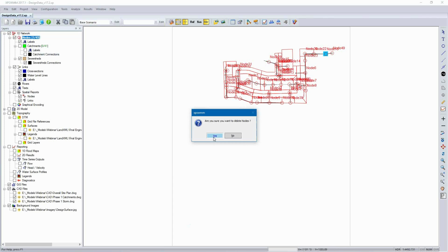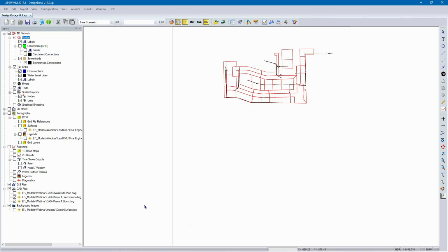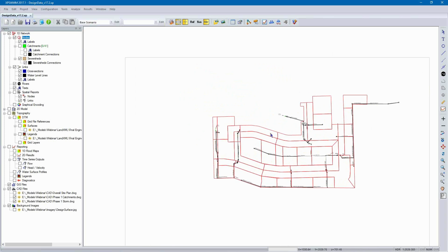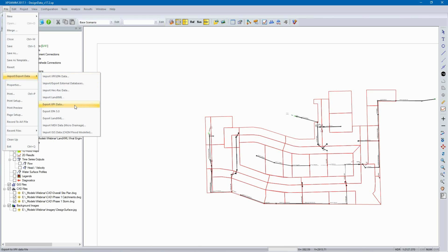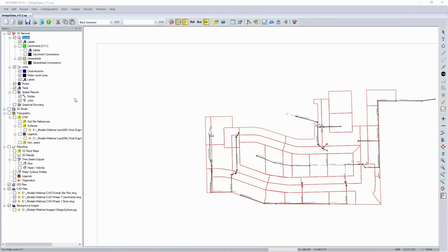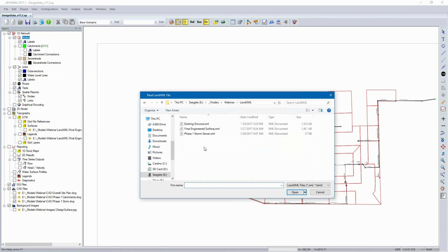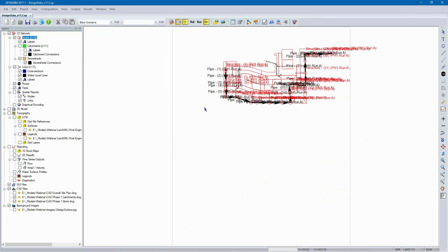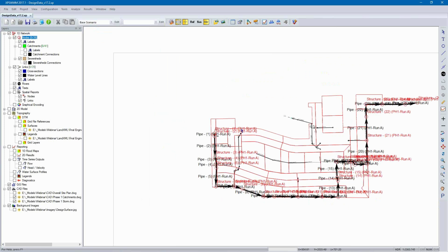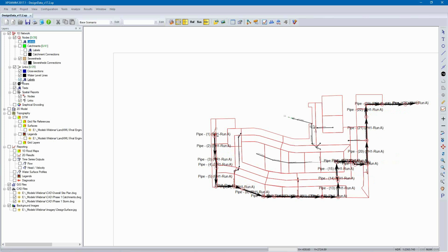Let's go ahead. I'm going to delete those. In this case, what if we have more design information, better design information? Maybe we've already created a pipe network in Civil 3D or GeoPack. Well, Civil 3D can export that pipe network to LandXML. And we can leverage LandXML and that BIM model here and actually generate somewhat intelligent elements. Zoom previous. Let me turn off some labels here.